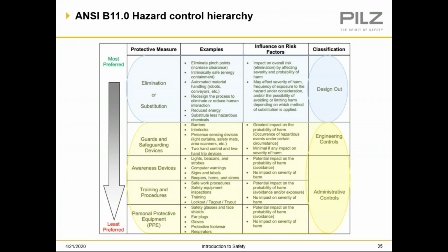After that, lights: you've got stack lights, beacons, strobes, horns, signage, a lot of different ways to make somebody aware that they're a hazard. And then there's training and procedures. So how do you work safely with this equipment? And again, I've said it earlier, this needs to include everybody that interfaces with that machine, not just the operator, and then including lockout and tagout. And then the last line of defense is going to be personal protective equipment, which is your safety glasses, steel toe shoes, earplugs, whatever is necessary in the particular job that that operator works in.